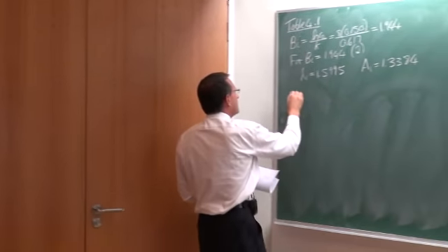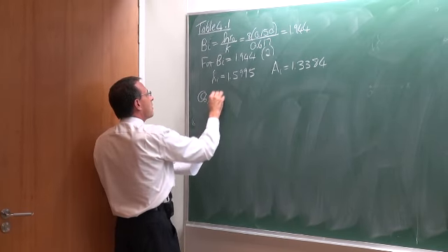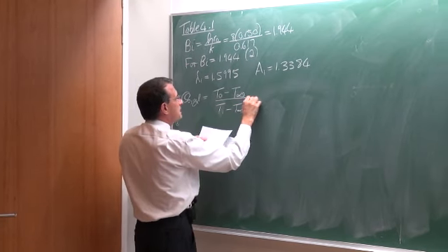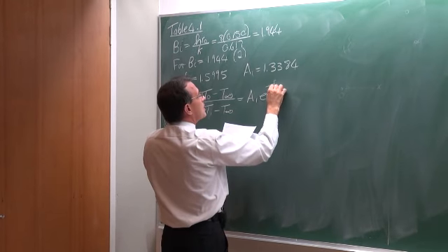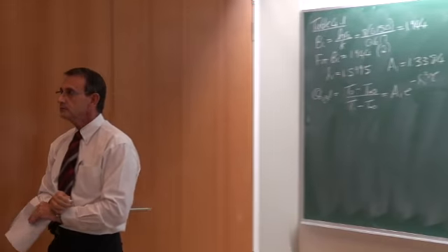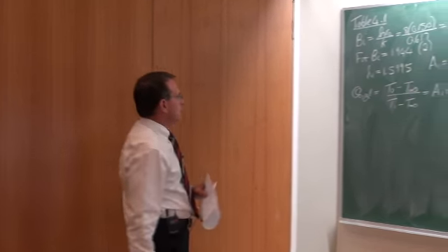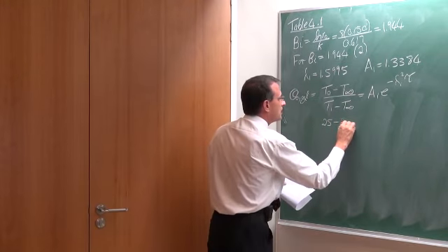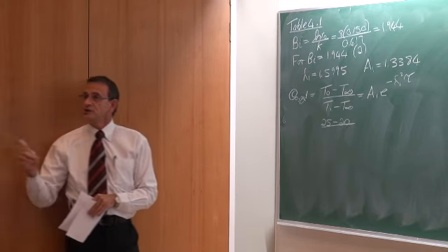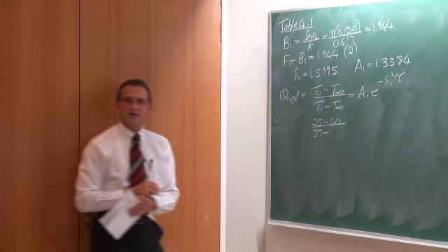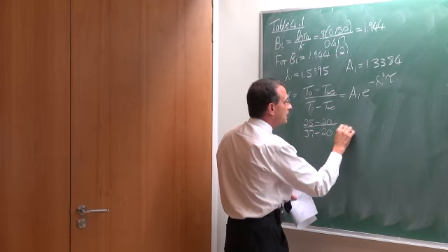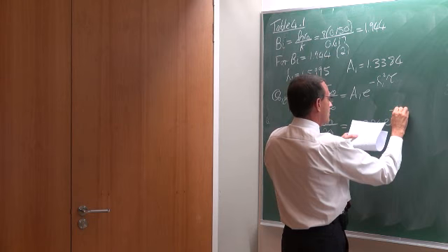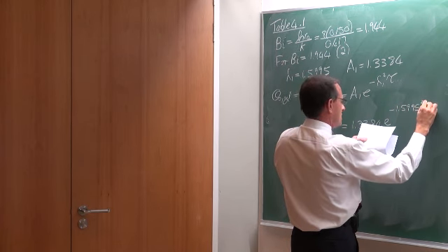So for that same equation, theta at the center for a cylinder is equal to the temperature at the center minus T infinite over the initial temperature minus T infinite, which is equal to A1 e to the minus lambda 1 square multiplied by tau. The center temperature is 25. The room temperature is 20. The initial temperature before the body died must have been at 37 degrees Celsius, and the room temperature is 20, is equal to A1, and A1 is equal to 1.3384 multiplied by e to the minus 1.5995 square multiplied by tau.